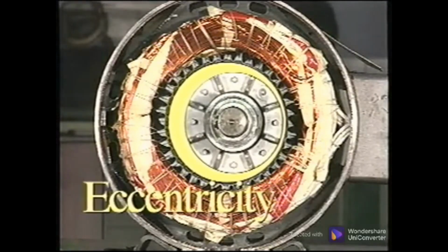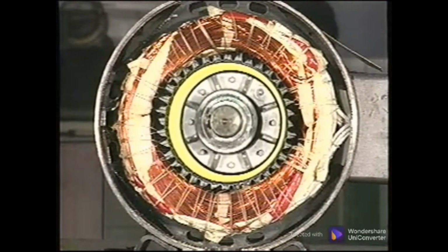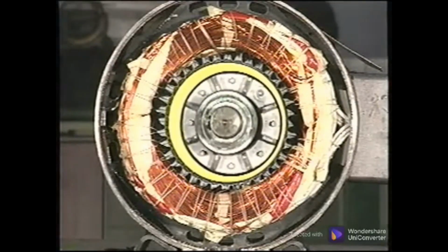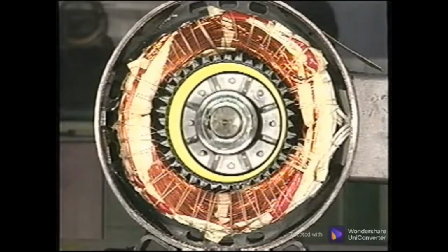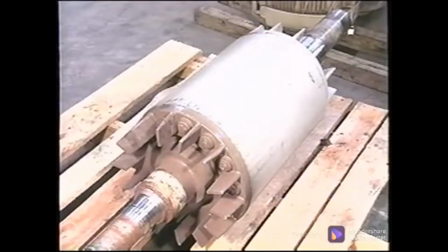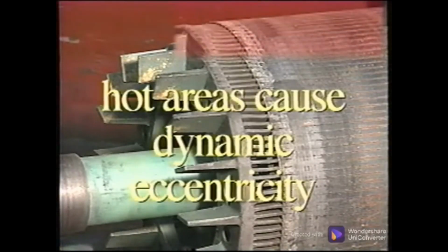There are several conditions that cause an eccentric air gap. If the center of the rotor is not in line with the center of its shaft, it will cause the air gap to be eccentric. Since the eccentric air gap changes positions as the rotor turns, this condition is called dynamic eccentricity. Both ends of the shaft must be concentric with the rotor, or the resultant air gap will be eccentric. If the rotor has open rotor bars that generate heat, the rotor will expand at that point, causing it to be eccentric and generate dynamic eccentricity.